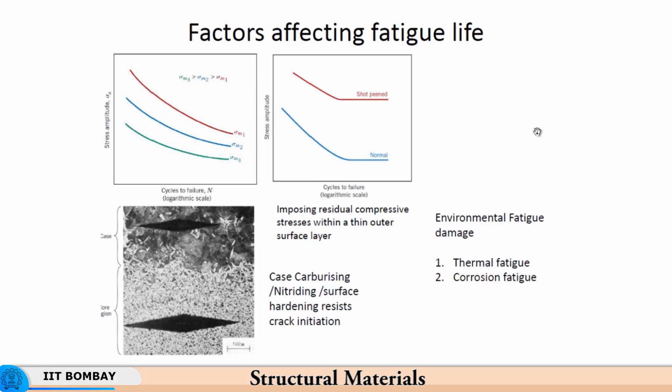The interior is soft. So many times during fatigue loading, the strains experienced here are relatively small, because of the very high load withstanding capacity of the case. The core is relatively soft and capable of undergoing a large amount of deformation, and therefore at the interface you have a discontinuity.